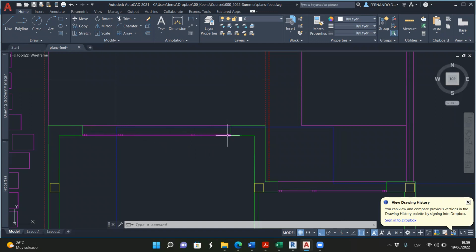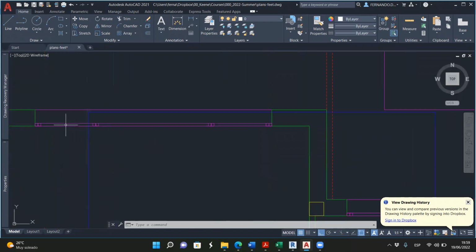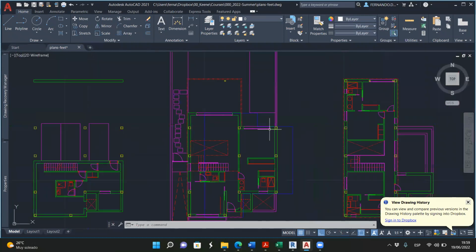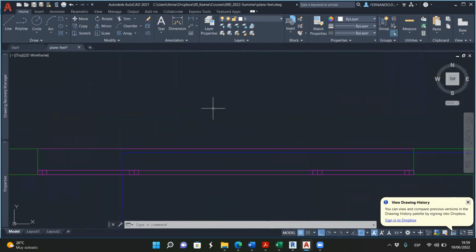Where does it come from? When we have a huge window like that one, having one piece of glass is not an option, because if we need to open something, then the openable part has to be smaller than the fixed one. Basically, having a huge piece of glass is very expensive. So in this case, you can see we have 3 parts, 1, 2, and 3. And here we have only 2, the openable one and then the fixed one. So we can always design our own windows.